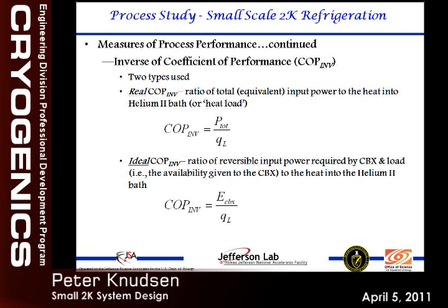That would be the COP inverse. Now, the ideal COP inverse uses the exergy calculation I just described. This would be the exergy flux supplied to the cold box divided by the heat load. Examining those two different COPs helps us to see different aspects, which I'll get into.